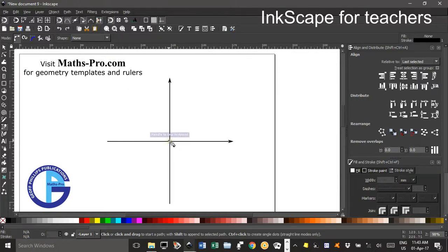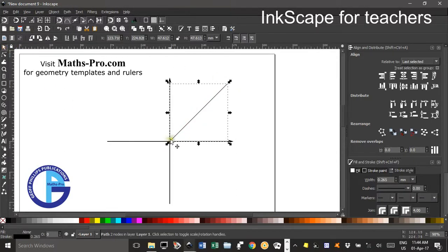If I now go, yes, that's snapped, click, I'll then hold Control and increments of 15 degrees are forced, I'll click and enter. Then I'm going to duplicate that, Control D to duplicate, reflect it in the vertical axis, Control, drag it across till it snaps there.